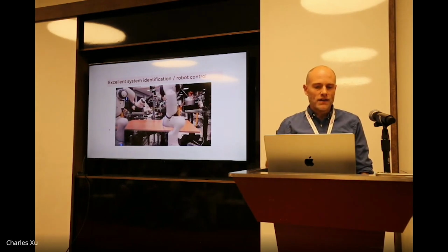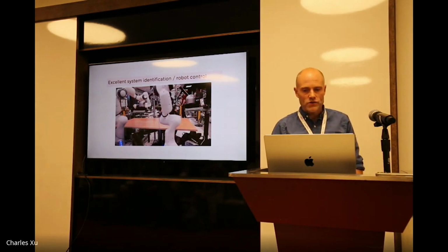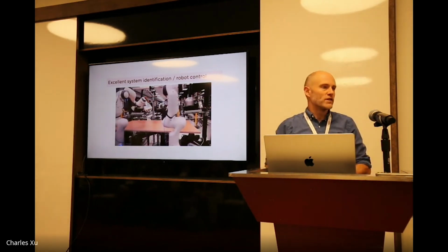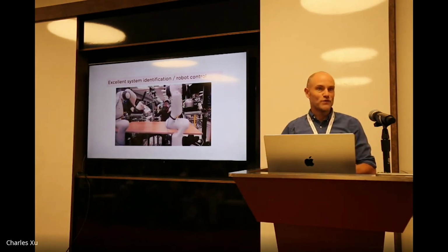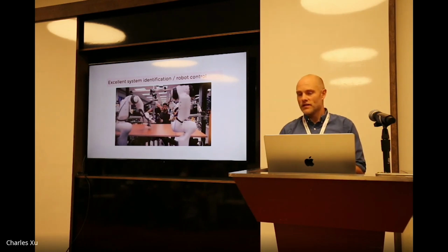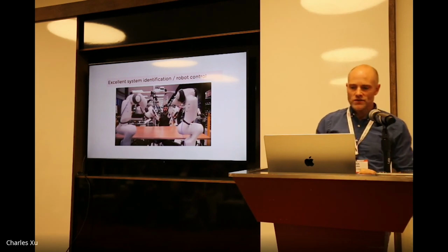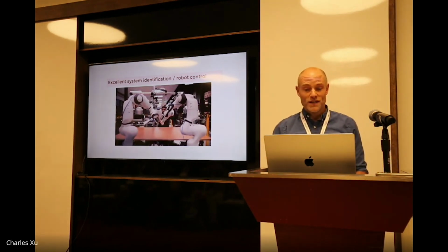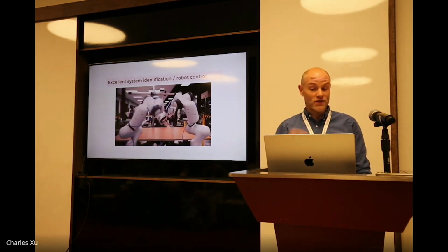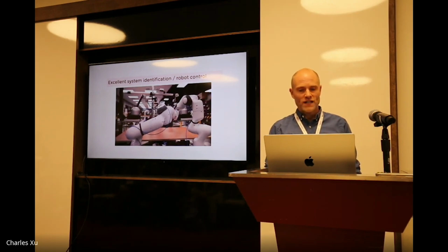It's built on excellent engineering, right? There's really good system ID, really good robot control. So this is an example of the human basically trying to make the robot collide with the table, and the robot is refusing because it's got a low-level operational space control with collision avoidance. Even when you try to jam the robots together and there's complicated collision geometries, right? Those are things we do know how to do in robots, and you can put that as a nice last layer of protection. Maybe it's our safety case, if you like, for making these things have robust rollouts.